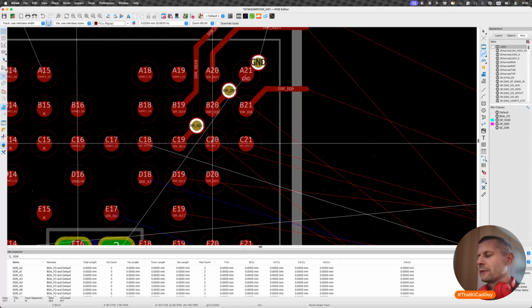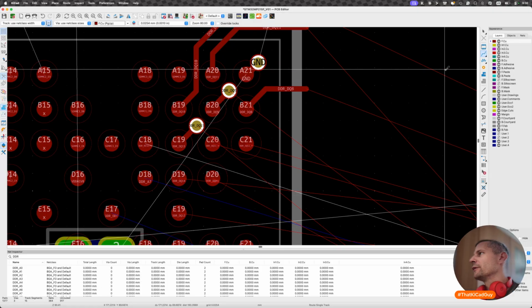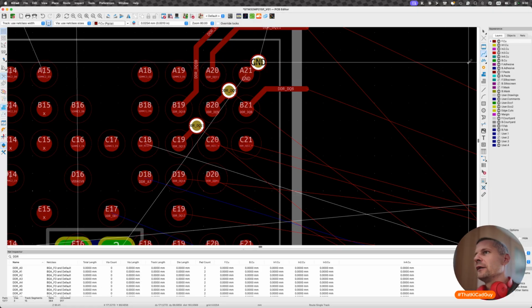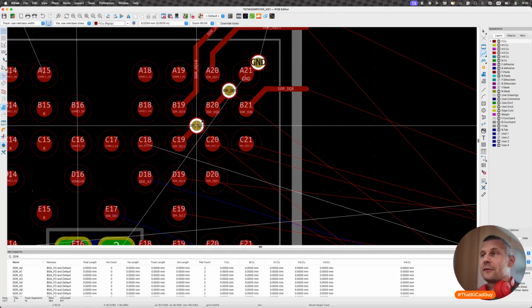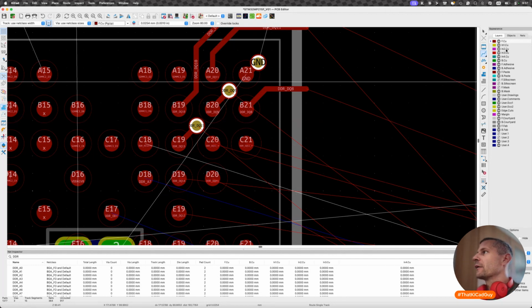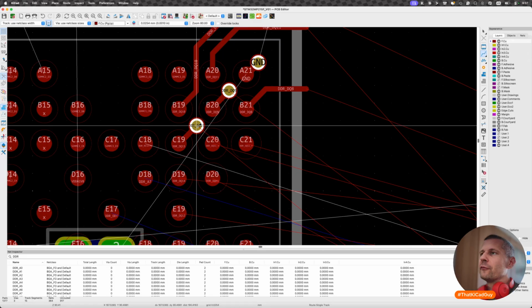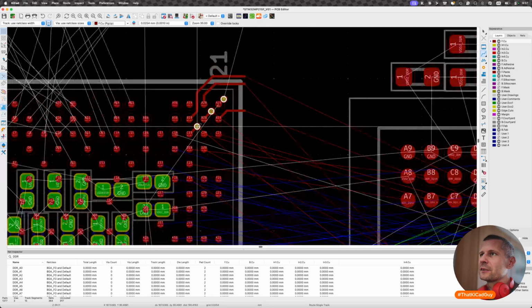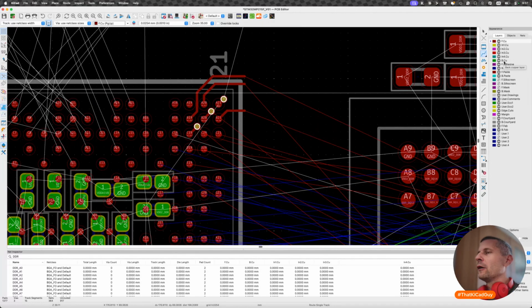Yeah, obviously, when we change the reference plane, we have to place a ground via, but we can't change the reference plane. It means that the second layer, the purple one, will be the signal layer for all the signals that have a via here, because we can't go to the bottom, because there shouldn't be a return path.